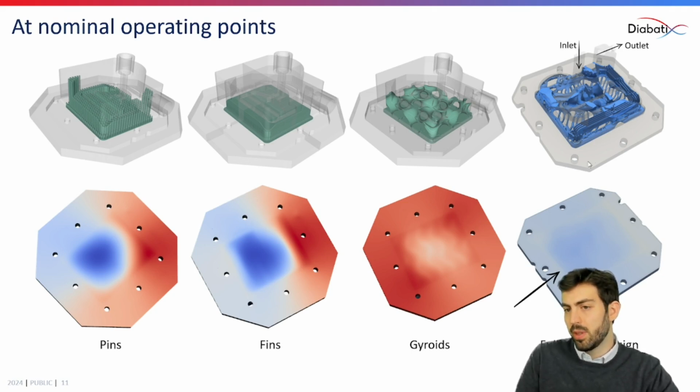In this case, we have also 3D printing, the same thing with the gyroids. But now the design, or ColdStream, has full design freedom of making a heatsink. So you see here that it came up with something very smart. It's trying to make the fluid go over the whole area with these channels, but also introduce some bypasses to fix the hotspots at the end, which in this case, this here is the outlet.